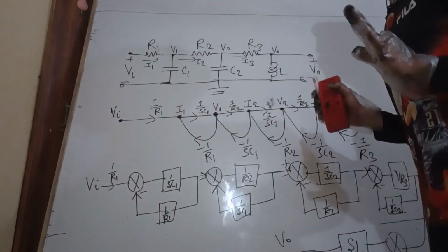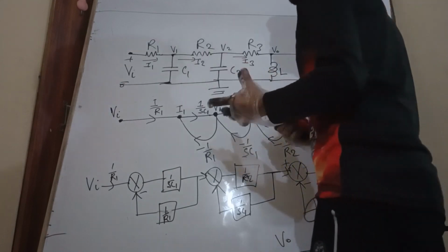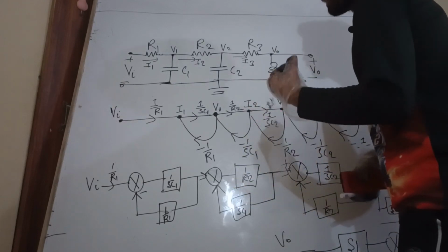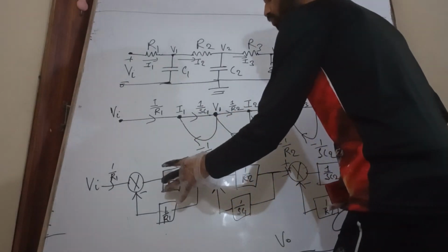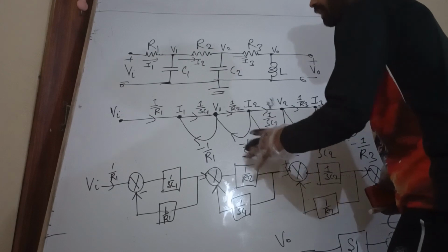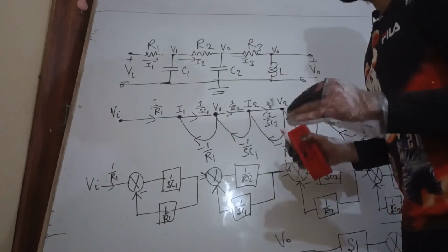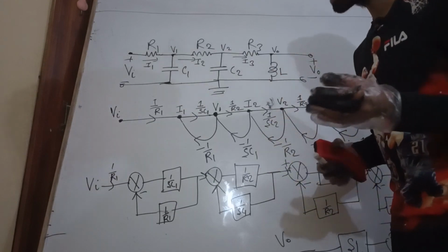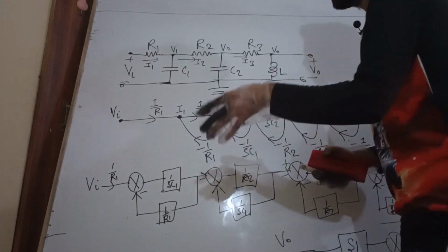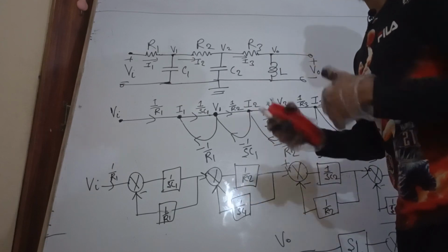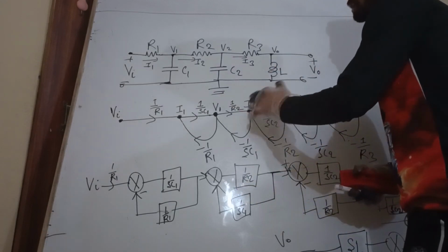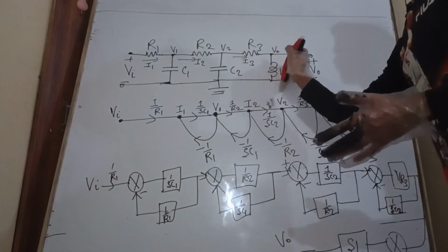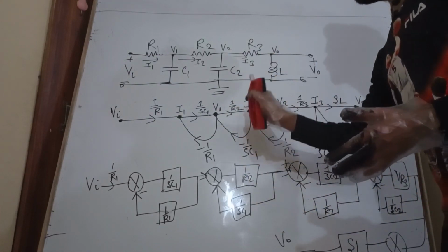So now we are very comfortable that the signal flow graph and block diagram are just forward path gain and feedback path gain, either admittance or impedance, where each node is either current or voltage in alternate manner. This is the way of representing this electrical network in block diagram and signal flow graph.